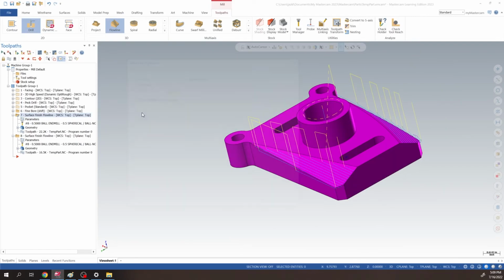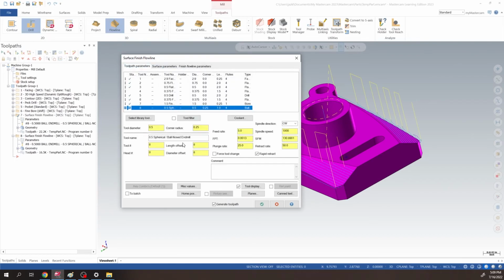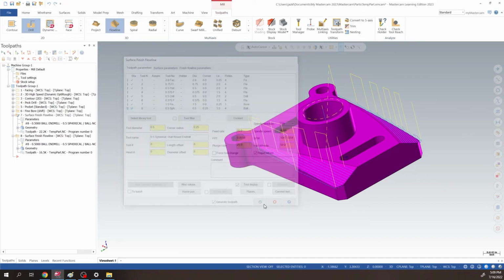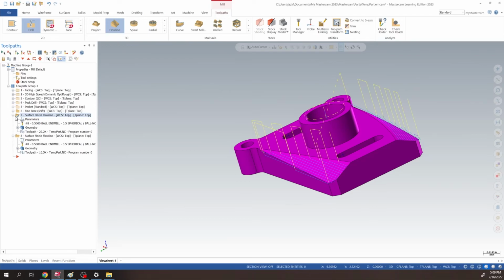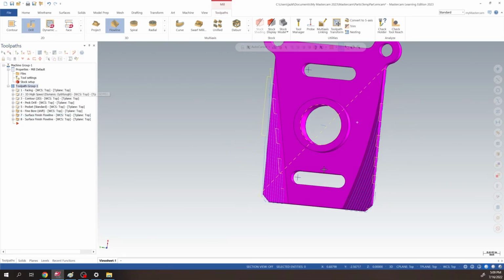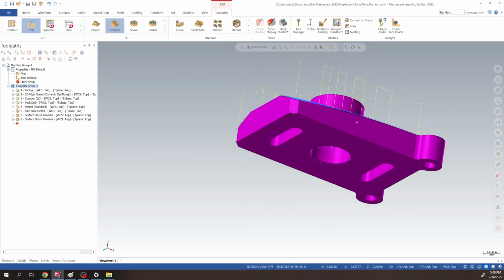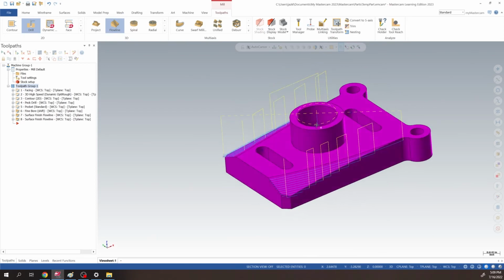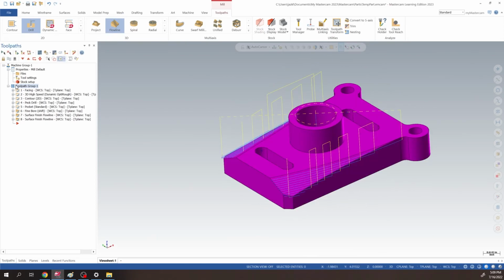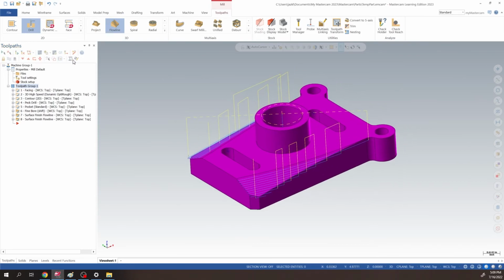And then on the parameters of the first one, I'm going to go back to toolpath, and then I'm going to set it to 8 grand at 60 IPM. Perfect. So I'm going to go ahead and hide that. So let's go ahead and click verify and see how this thing machines and see if we missed anything. And then we can go back and add anything that we missed.